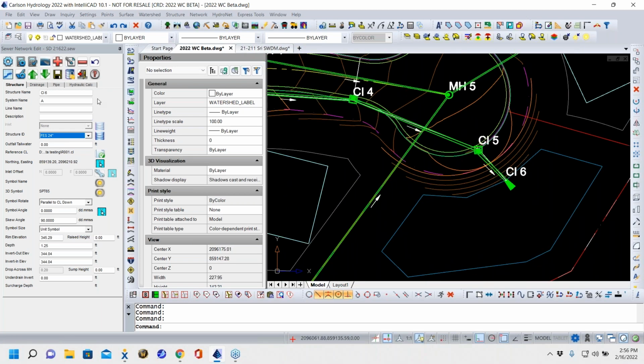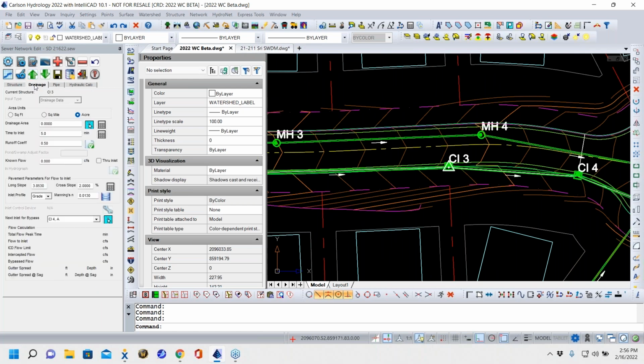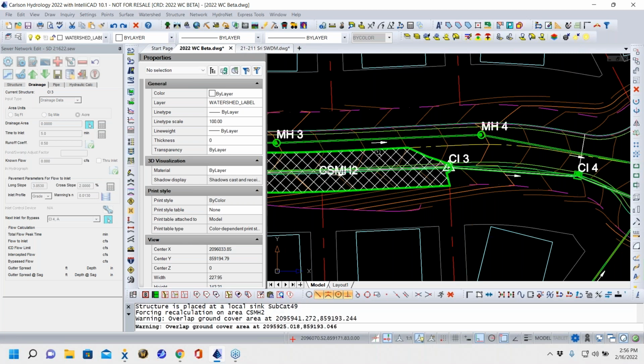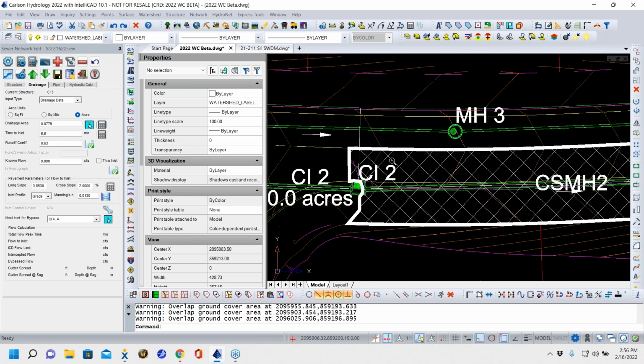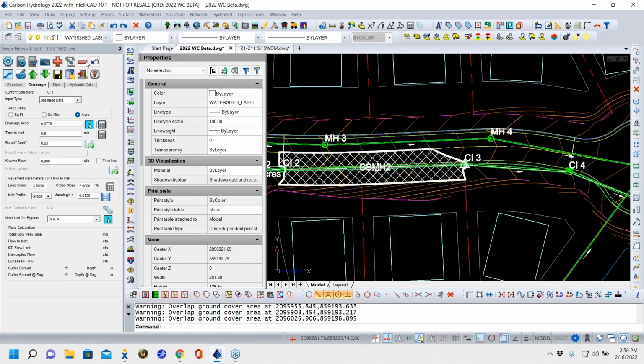So now, if I go back upstream, let's just make sure I'm going upstream. I want to make sure I've got drainage areas for all this mumbo jumbo. Let it calculate on its own. Should come up and be this half of the road. Yeah, see, that's pretty good. Wrapping around catch basin 2, that's pretty cool. And so then we'll go downstream and you guys can see the drainage areas. You can see what it calculates as your runoff coefficient.